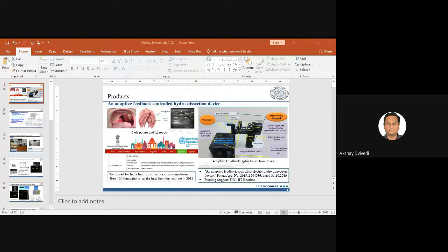What is the end result? Here we have two cases. One is with respect to a smooth tool, and the second is with respect to a rough tool, all other parameters remaining the same. When the experiment was conducted, it was identified that the depth achieved with the rough tool is far more as compared to what you get with a smooth tool. Additionally, the flatness available with the rough tool is far better as compared to a smooth tool. Now, is this fulfilling certain customer requirements?